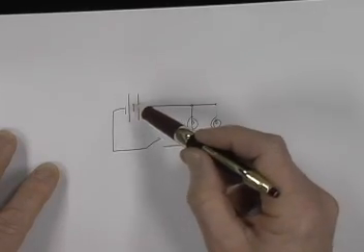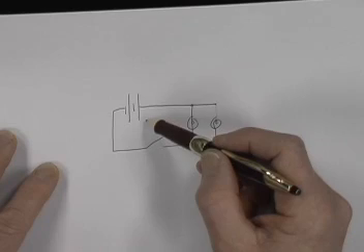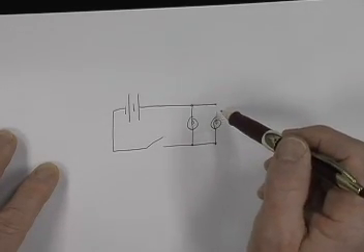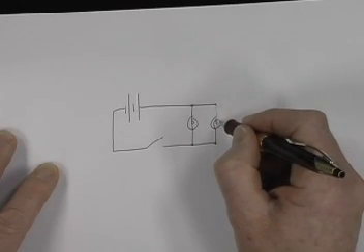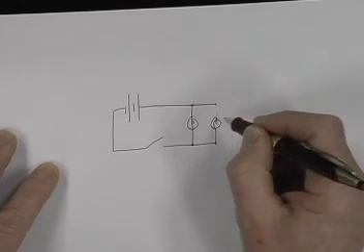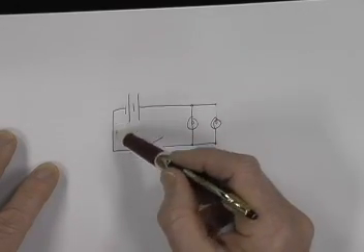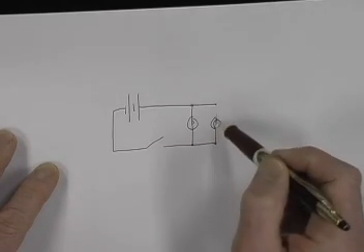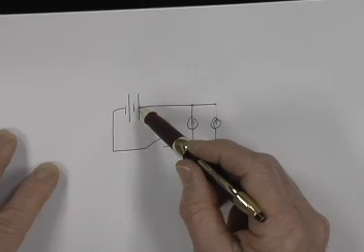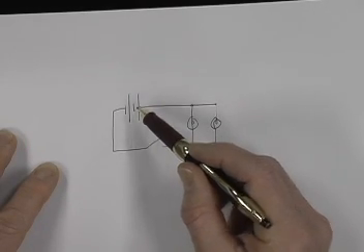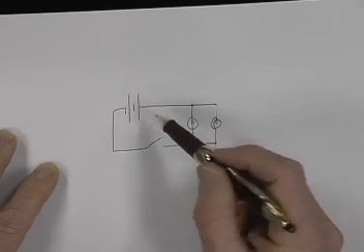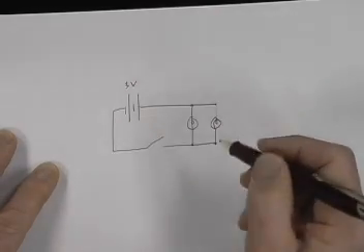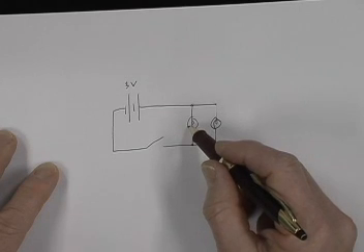Now it doesn't really matter where you put the different elements in the circuit, because of course the electrons will take the easiest route, and the easiest route will involve going from here through the switch and then through either lamp and back again to the positive terminal. So when we have two cells in series, we actually have roughly 3 volts, and both of these lights will be quite bright.